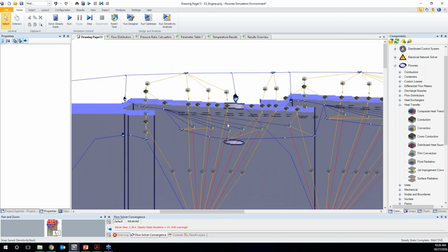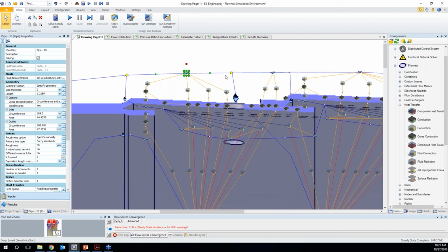So again, if we look at an individual panel right here, we have air coming from a duct section that represents the annular flow path. It's coming into this slot, and it's cooling this air. We have some dilution holes as well. They don't really affect the heat transfer right here.